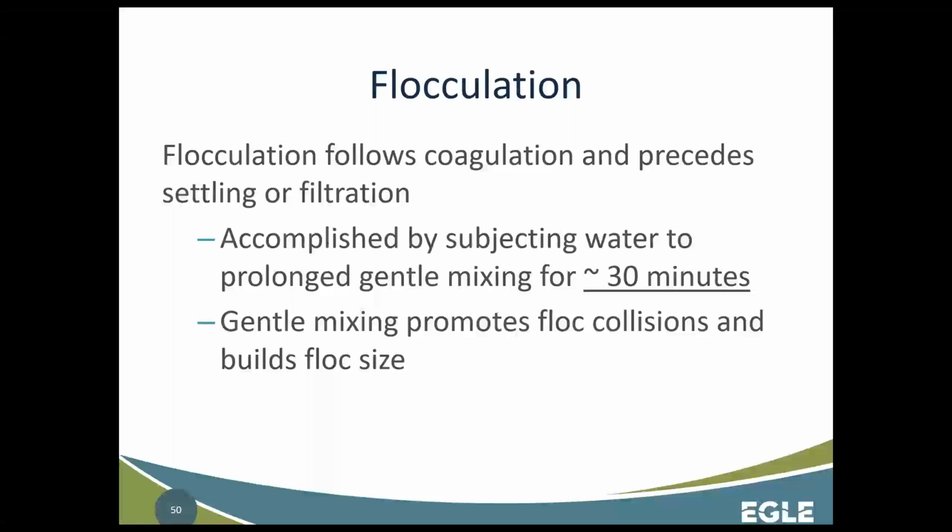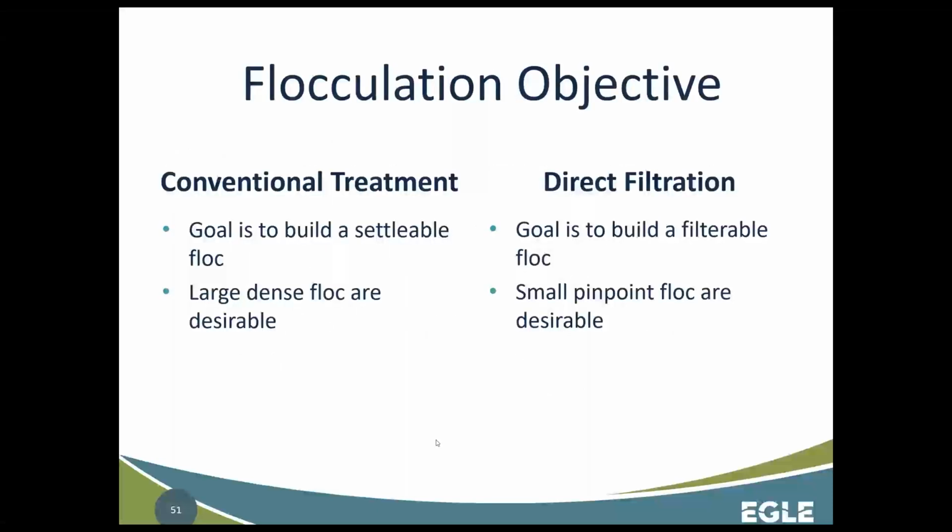Ultimately, there's some important things to keep in mind here. If you're trying to get a sweep floc or a bridged floc, you don't want to have high mixing energies in your floc basin. It's going to break up that floc that you worked so hard to create in the previous steps. Again, conventional treatment, you want as much of that turbidity to settle out in the settling basin. It's going to get you longer filter runs, and it's easier to remove the sludge from the settling basins than to manage the filter backwash water, depending on where it's going.